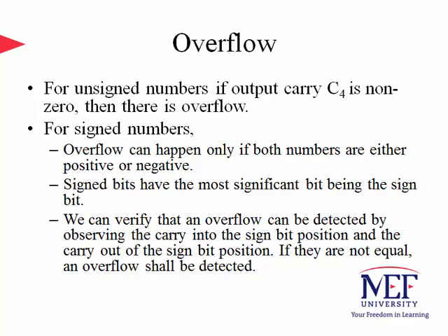For n-bit unsigned numbers, if the final carry out bit is non-zero, then we locate an overflow problem in our system, because the arithmetic operation produces n plus 1 bits to represent the output, which is not possible in the hardware. If you had a piece of paper to perform the arithmetic, you wouldn't have this problem, however. But in hardware, you've got only a limited number of bits to represent a number, which is n in our case.